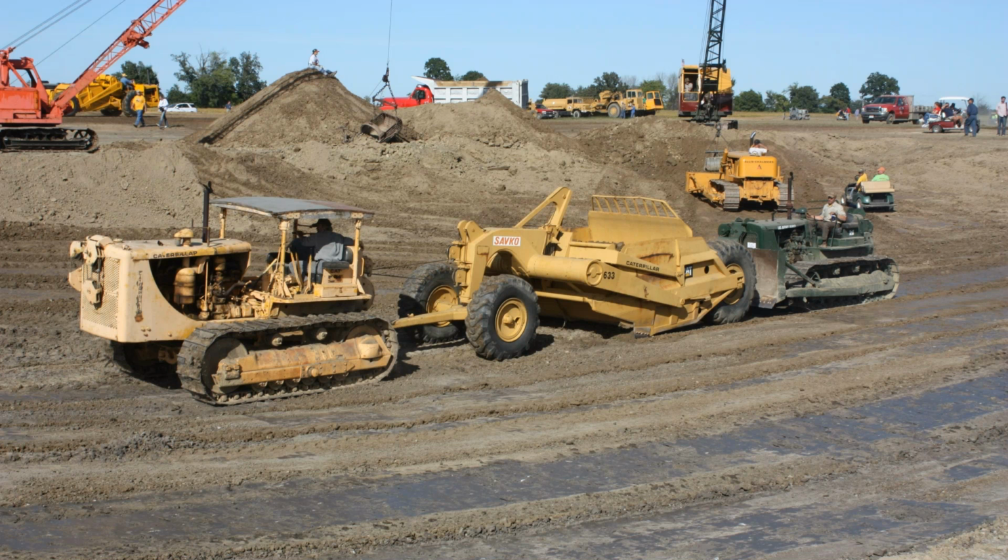So we don't see this type of operation with a single bowl very often. If you look up, this is the start of a project, not a lot of safety equipment in view, but you can see in the background there are open bowl scrapers being moved around. Those open bowl scrapers, there's 3 of them, right? 1, 2, and 3. Those open bowl scrapers are going to be getting ready to cut, and you can see the cut marks from the bowl as the bowl is engaged. This cutting blade is here, the apron is up, and the hydraulic controls from this vehicle are controlling this cart.